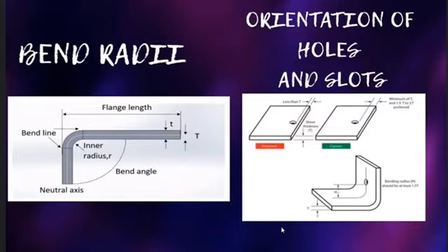Holes and slots. Keep hole and slot diameter at least as large as the sheet metal thickness. Hole diameters less than the sheet metal thickness result in higher punch loading, longer burnishing in the holes, and expensive burr. If the hole gets too close to an edge, a bulge can appear near the edge. Spacing between holes should be at least 2 times the sheet metal thickness.